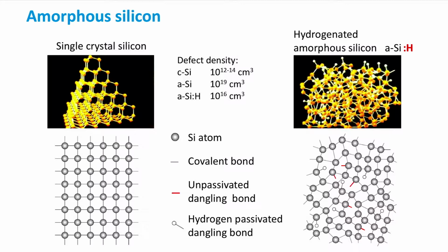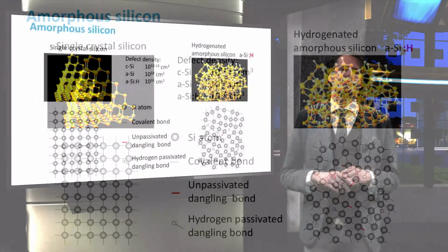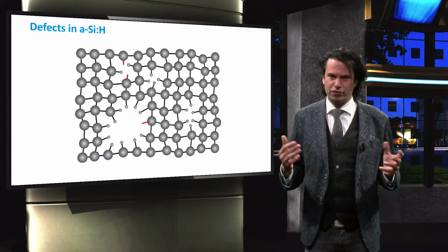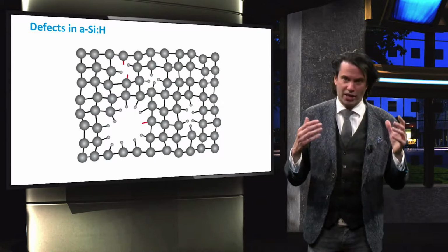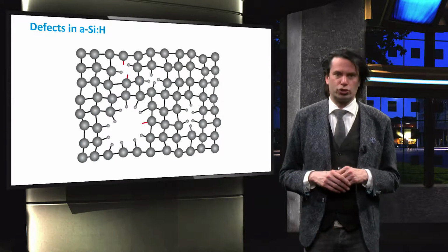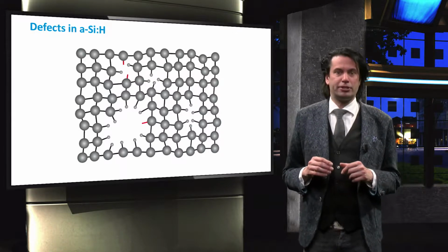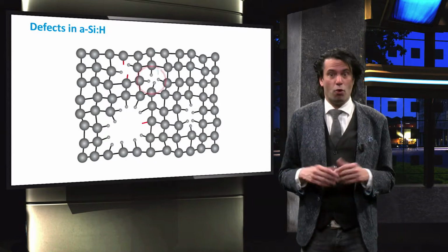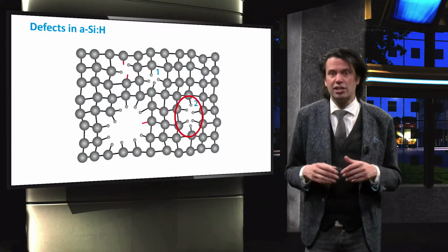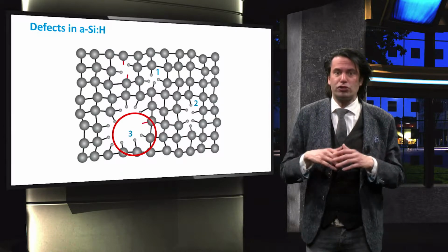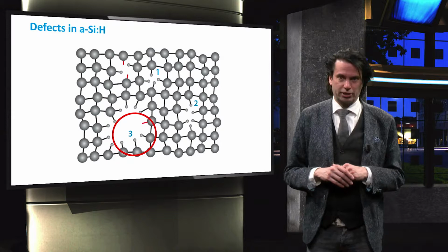Defects can also be purposefully introduced in the amorphous silicon lattice in the form of P or N-type doping. The dangling bonds are not distributed homogeneously throughout the amorphous lattice. They rather tend to group in small clusters. They can thereby form a number of typical defects such as monovacancies, divacancies and nanosized voids with a diameter of several nanometers, whose surfaces are mainly covered with monohydrides.